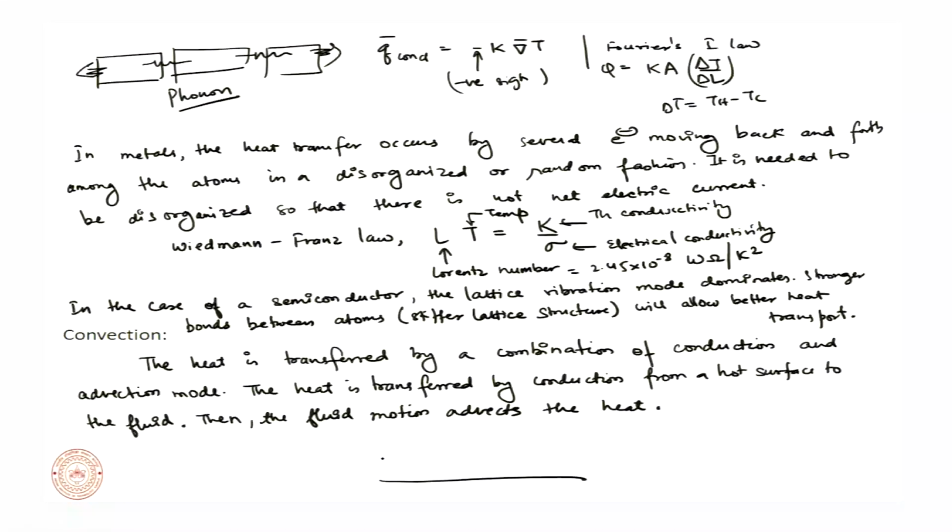So we can take an example of a boundary layer. So this is a flat plate material at a hot temperature T hot and the surrounding is at a cold temperature T cold. Our boundary layer looks like this. So say that we have two boundary layers. We can have a thermal boundary layer and we can have a momentum boundary layer. So we will talk about boundary layers later. So this is our profile. For those who know what a boundary layer is and what a fluid is, they would appreciate this mode. So the fluid is flowing over a plate and this is a velocity profile. So this is your u as a function of some height y.